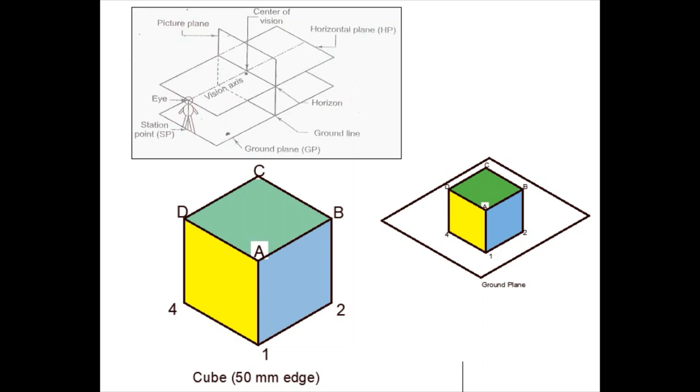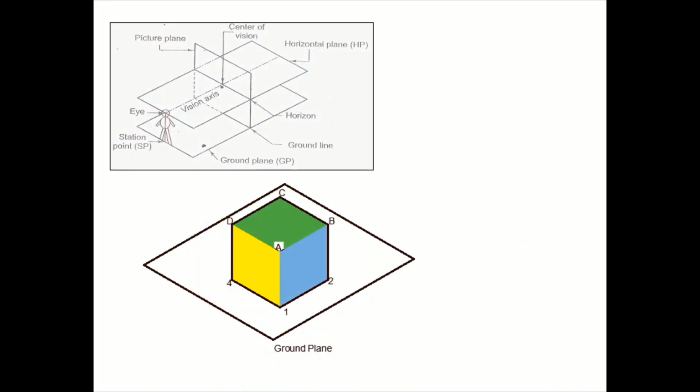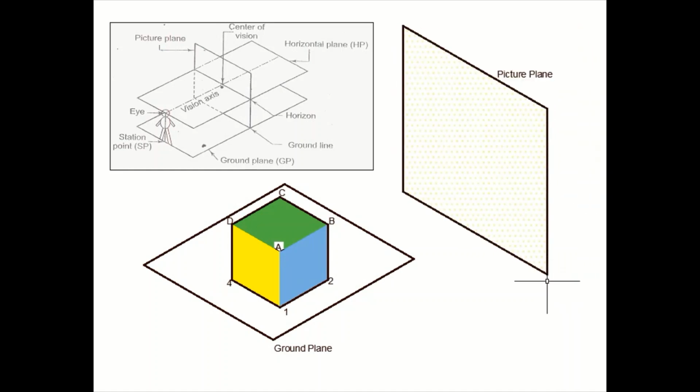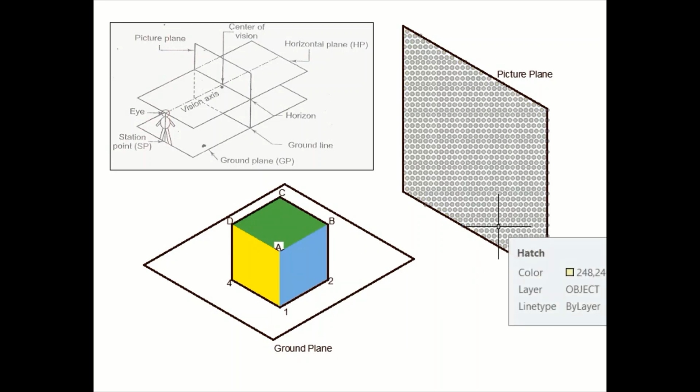The next element to be introduced in the concept of perspective drawing is the picture plane. The picture plane is an infinite sized vertical plane. Whenever we are making the one point perspective view of an object, we need to ensure that the face of the object which is available to us in the front view must be touching this picture plane completely.